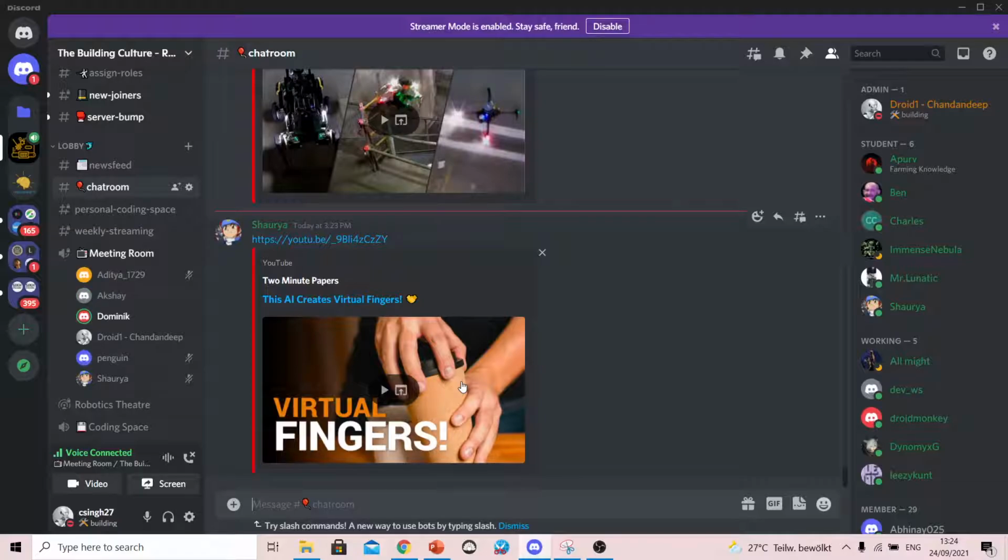Yes. So basically the forces that are created by contracting those tendons. What happens is the skin, the soft outer layer of this hand, is deformed or pulled on, and then because the outer layer is connected to the foam core, it pulls the foam core into a certain shape. Again, there are no joints, so we can't really estimate any force or any joint displacement. It also depends on how good a friction we are getting between the object and the actuator at the point of contact. Can I assume that? Yes, of course.